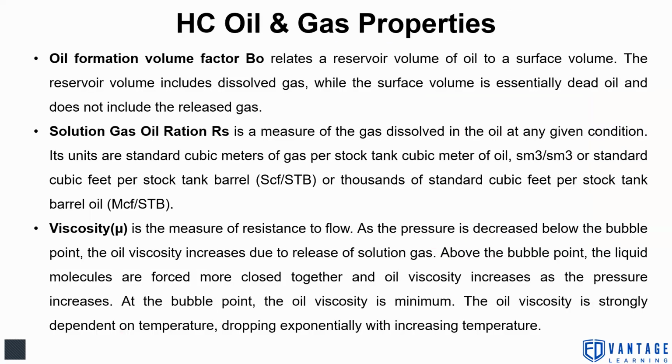So this oil FVF relates reservoir volume of oil to surface volume. The reservoir volume includes dissolved gas, while surface volume is essentially dead oil, with no dissolved gas. Similarly, solution gas oil ratio, Rs, is a measure of the gas dissolved in the oil at any given condition. It has the units of SCF per STB, or thousands of standard cubic feet per stock tank barrel, MSCF per STB.